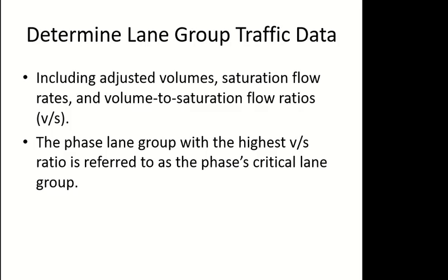Somebody will tell you, I want a signal at this intersection, and I will have this many vehicles going straight, this many turning left, this many turning right, from this direction, this direction. So this is input data. The demand volume is input data. What you are calculating is saturation flow rate, and for saturation flow rate we have a base value which is multiplied by multiple adjustment factors.